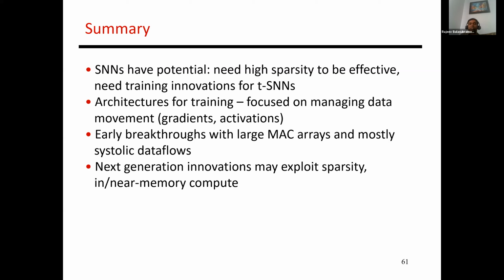So the way the landscape works is, we are going to build billions of these chips in the next few years, right? So a large number of those chips are going to be deployed on phones or in a self-driving car and so on, right? And so, if I'm Tesla and I'm building a chip that's going to go in my car, I know that that chip is only going to be doing inference, right? And so, I should build a chip that is focused on inference. Maybe I build something like Simba, right? Where Simba had these relatively small buffer structures. Now, if I took a chip like Simba and tried to deploy it in a Google data center that was doing training, it would behave really badly, right?